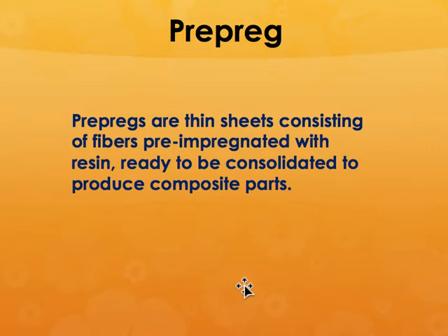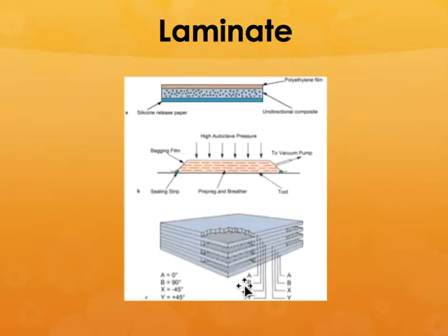So you only have one single layer of fiber tows, either as a single tow, or you may also have multiple tows that are woven into a single layer of the weave. You cut that and you place it into the mold, or place it in whatever shape and form that you want in order to make the final component. And then you have to laminate it in order to get the final shape.